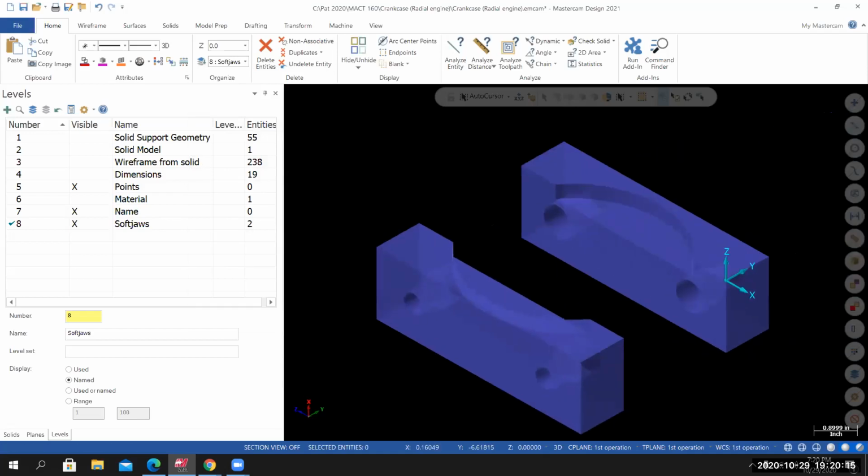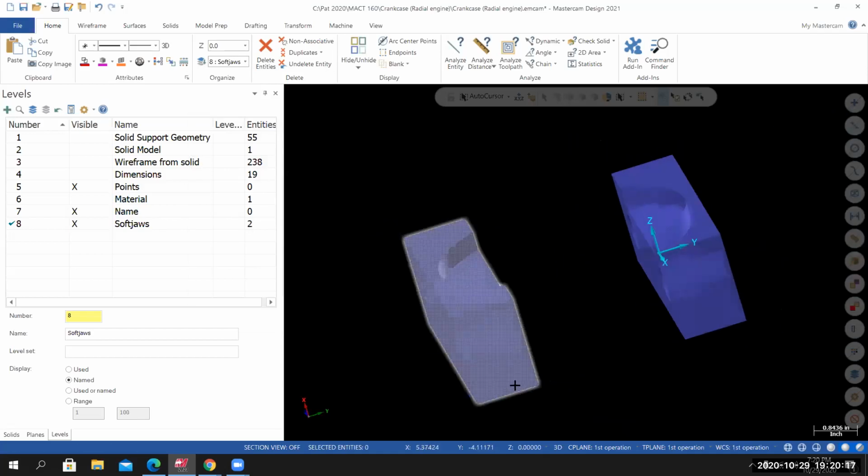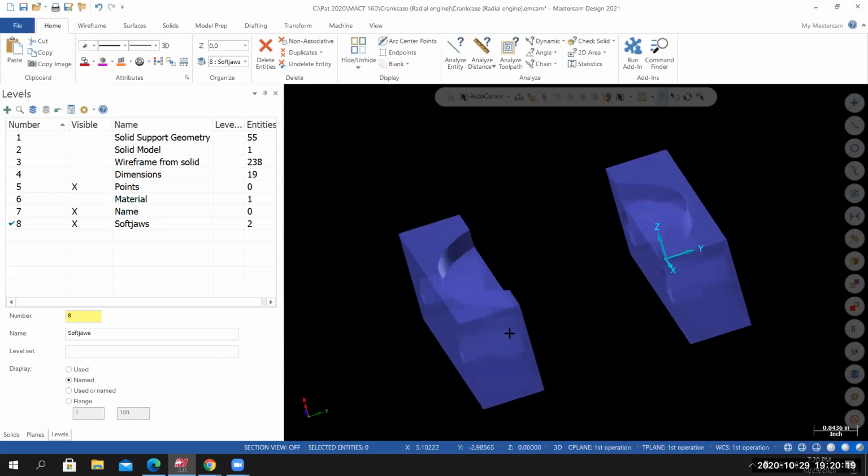Yep. So yeah, and I've had people do this in the past where they cut a soft jaw and they don't secure the jaw on the movable vise, and it vibrates. They get a lousy surface finish, and usually it can damage the tool depending on the material that you're cutting.